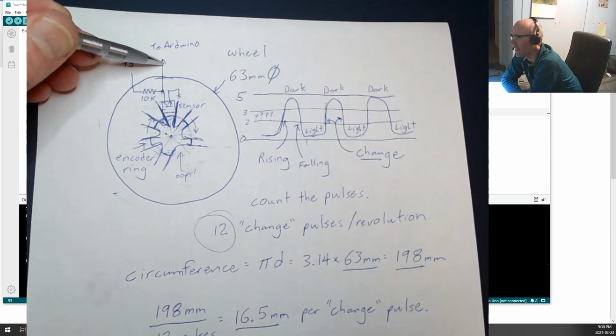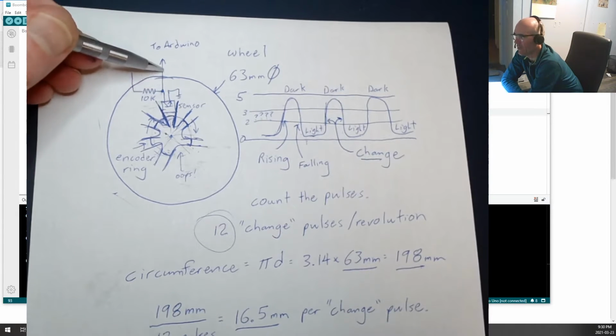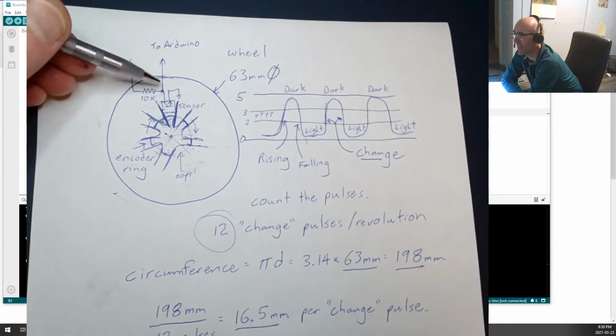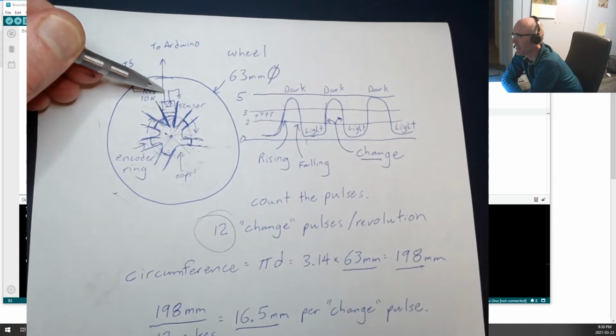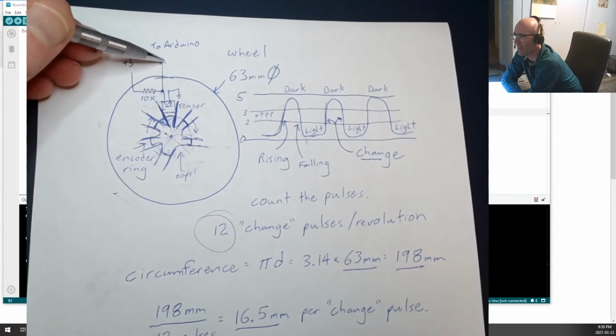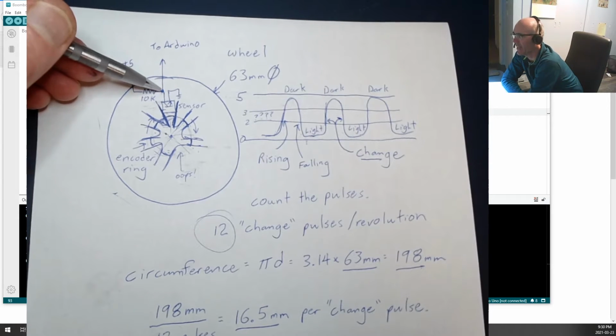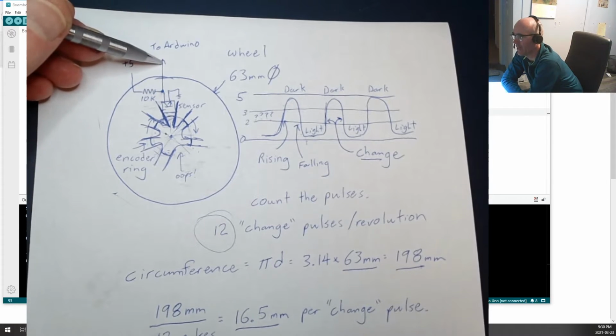Now on our edge detector, we had it pretty easy because that was tied in to an analog pin. So we could take an analog reading off of that and find out exactly what voltage that was at. Well, we've got these tied into a digital pin because we need them to trigger an interrupt, and we'll talk more about what that is a little bit later on. But this goes back to our Arduino on pin number 2 and pin number 3, one from each side, because that is where our interrupt pins are located.